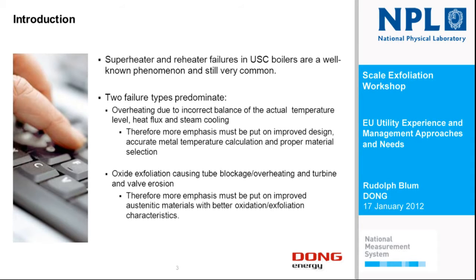Before that time, we had very little problem with exfoliation. In our fully ferritic constructed boilers, we now and then could have problems with the inlet to the turbine due to blockages of relatively thick oxide scales coming from the steam line or from the large stage of the superheater, due to exfoliation after being in operation for far more than 100,000 hours.